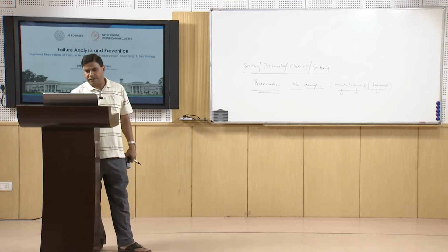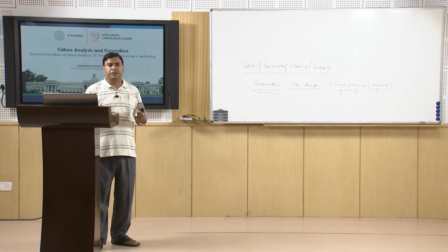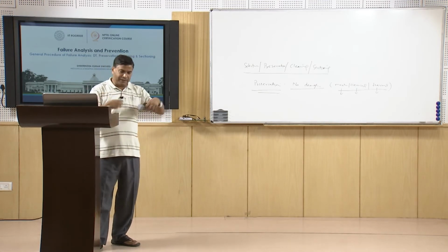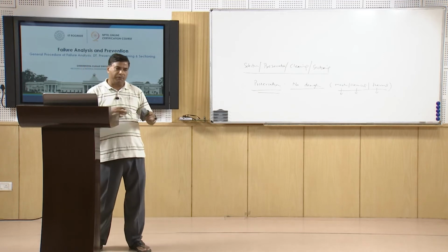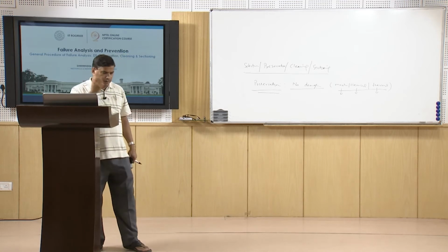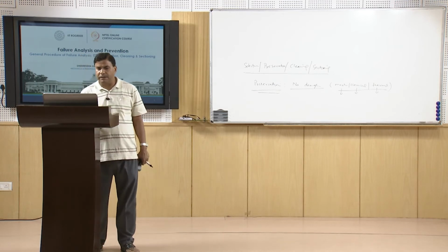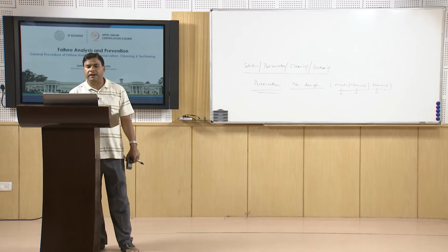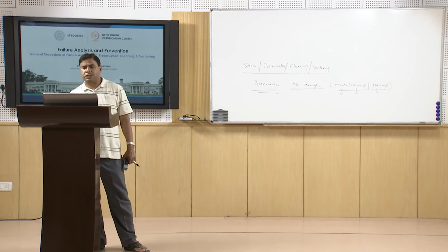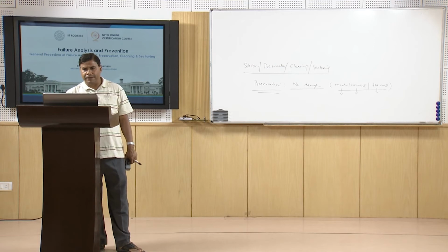So, touching of the fracture surfaces should be avoided, and we should not try to fit the ends of the fractured components, because this will further damage the fracture surfaces, modify their morphology, and make the job of the failure analyst further difficult. So, no fitting of the fracture ends, no touching, proper protection of the fracture surfaces during transport, and striking of the surface with other objects is also to be avoided.